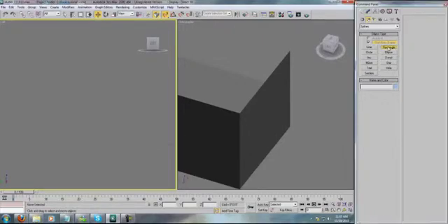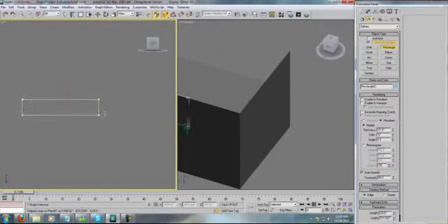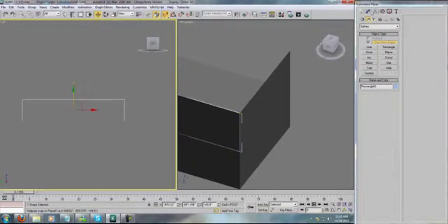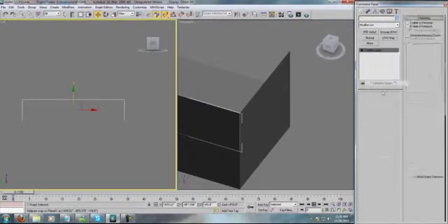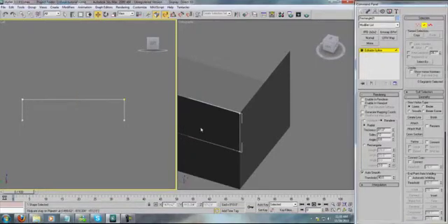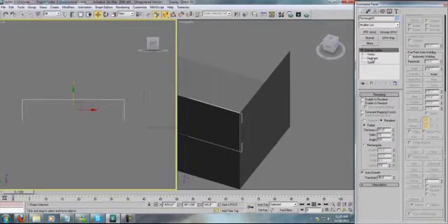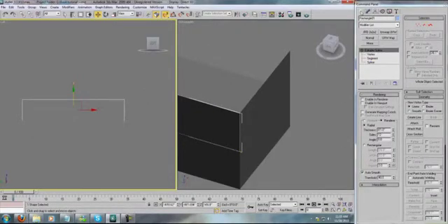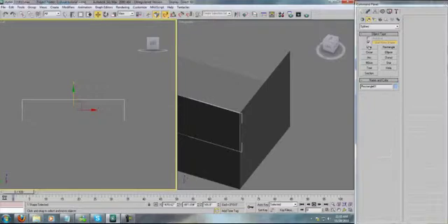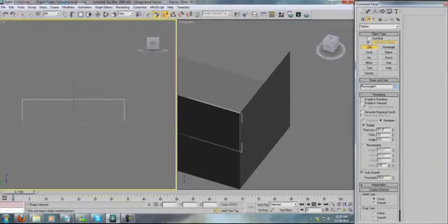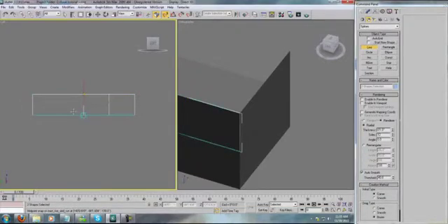Now let's go to Spline Modeling, hit Rectangle, and just make a rectangle that goes for this entire length. I'm going to go in here, create editable spline, go to our second spline tool, and then detach that. Now I'm going to go into our spline modeling, go to line, unselect this, which will make it attached to our previous shape that is selected. And I'm just going to bring it down here.